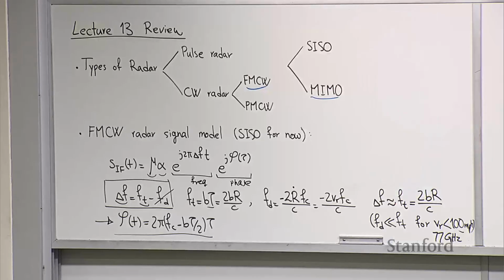So it's always full IQ. Yeah. Physically, you get out of your ADC. You can't, in circuits, have complex signals. So it gives you two data streams, one for I, one for Q, as you know. And then in DSP, you mix them and make a complex signal out of it.